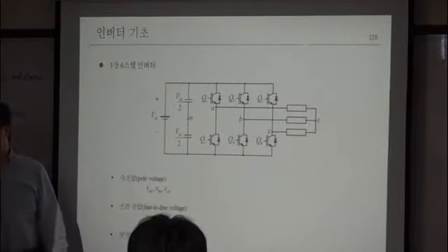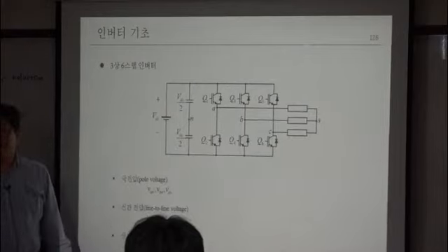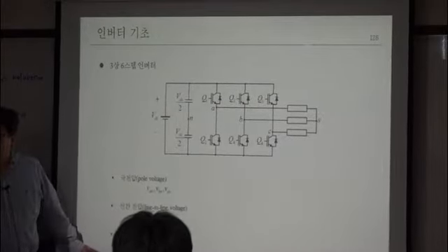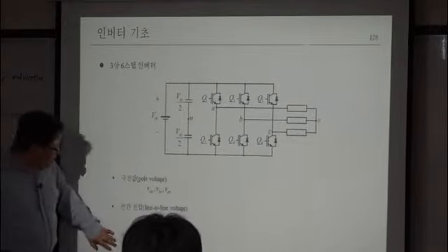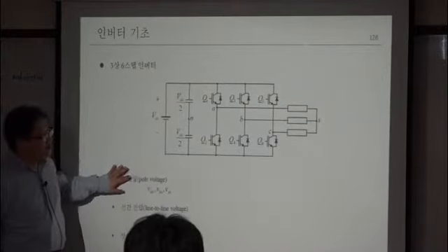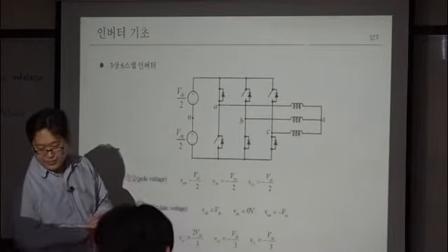Then, from the viewpoint of your load, which one is important among the three voltages? In your viewpoint, which one is important? Phase voltage, right? So, phase and line-to-line voltage are important. The pole voltage is not very important to your load side. Okay.